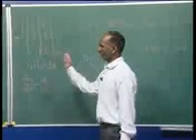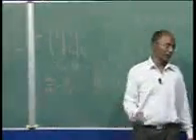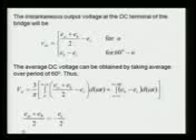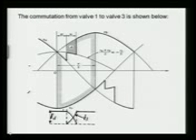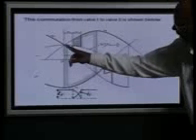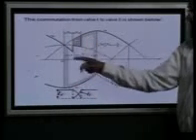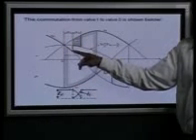We will see again when we draw the voltages. So this is your average, and you can see from this diagram, this is the same case. Once this valve is fired here, then this period will be u, but we are delaying it, so EA continues to conduct, meaning valve 1 continues to conduct.